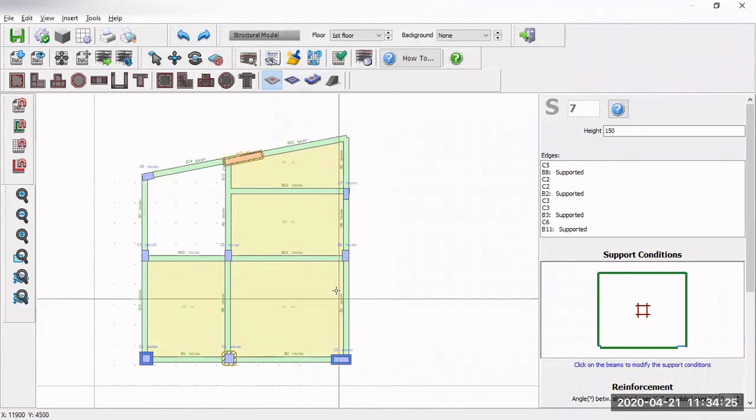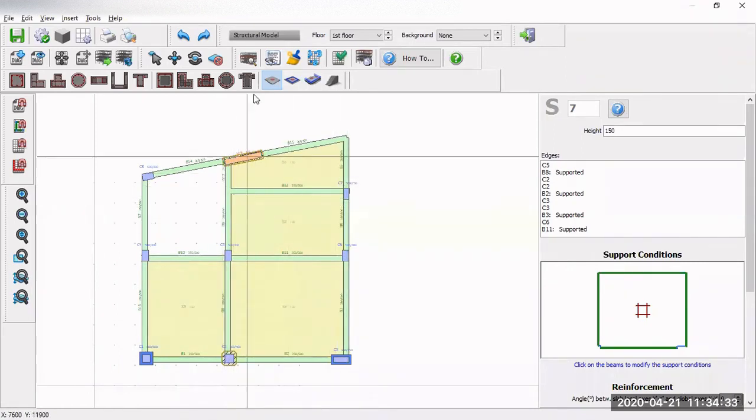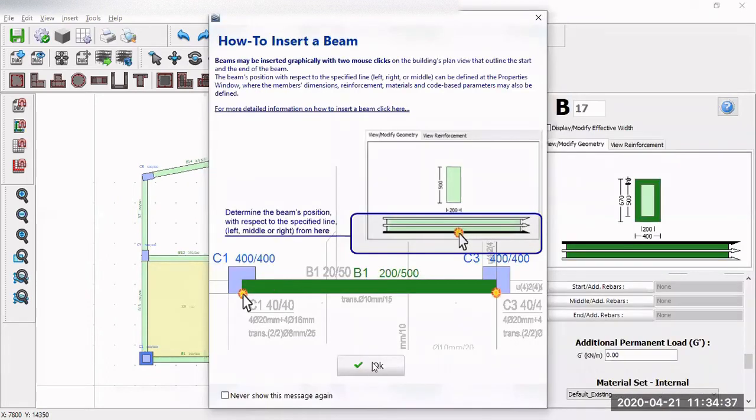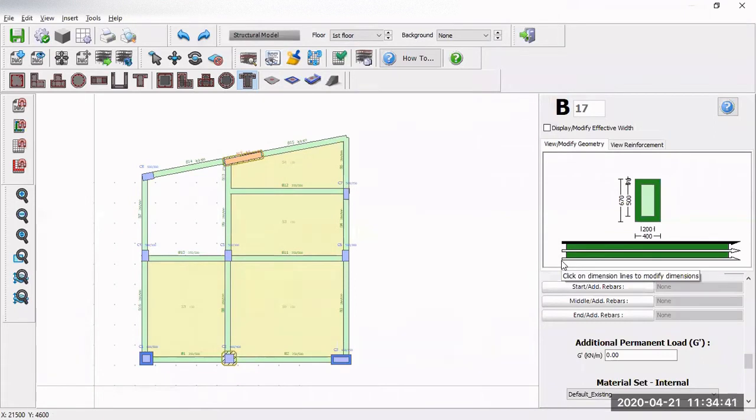Okay. Once we're done with that, the next step is I try to do the strengthening for the beam, which is this beam here, this beam and this beam, retrofitting the beam. For the beam, I'm going to use this function, insert jacket beam. Click OK. All right. Similarly, we have to define this. The original size of the beam itself is basically 250 by 500 actually. And in this case, we're going to do the same thing as the column. We enlarge 100 mm the whole parameter of the cross section. So the width will become 450. All right. So in this case here, the top, I assume that maybe we increase to 100. Oops, 100 here. And then this one I will increase to 700. Okay. So this is what the size of the jacketed beam looks like.